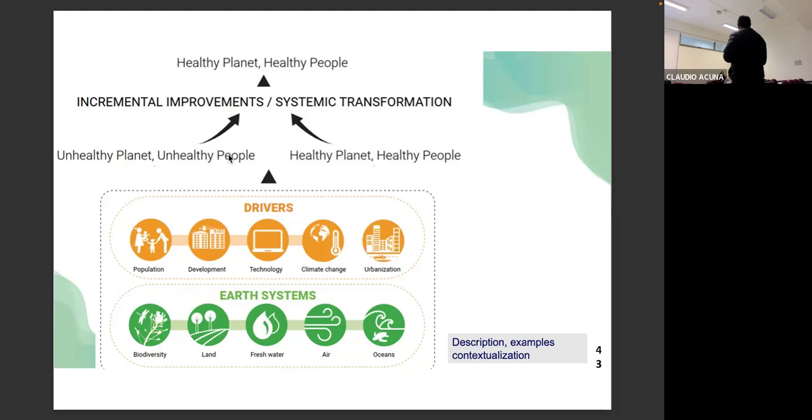She's specialized in thermodynamics, working in Aspen HYSYS. Let's say a Brayton cycle, you end up with 65% efficiency, no more than this. Remember, the thermal efficiency for thermal processes is 1 minus the lowest temperature over the hot temperature, that is our reference. But we have 65%. Not that good. So when we have 100, 120 degrees, we use different cycles. We don't use water, we use an organic cycle.